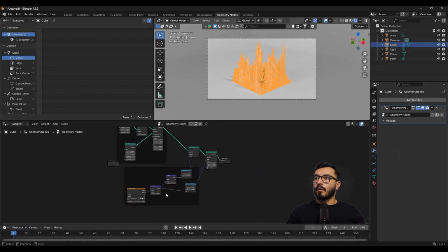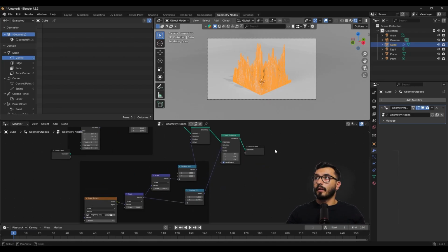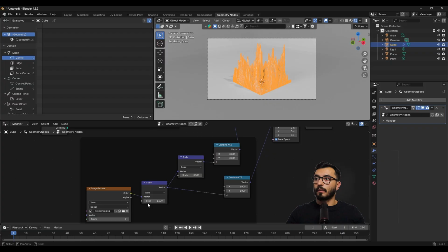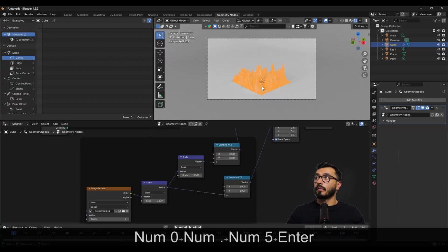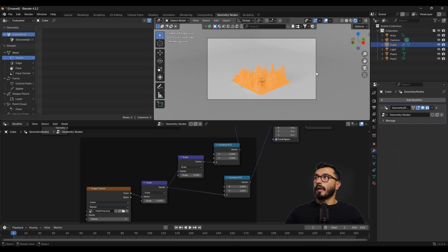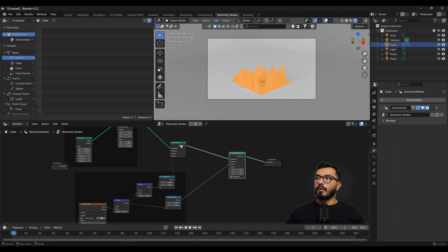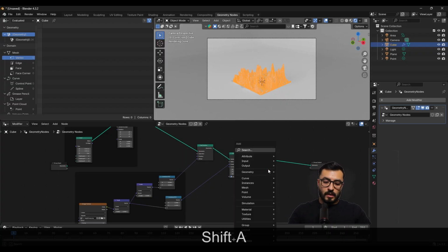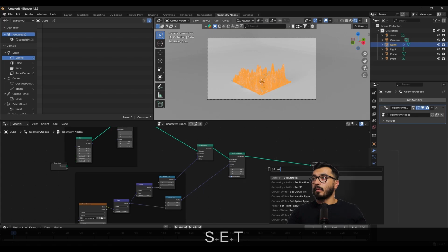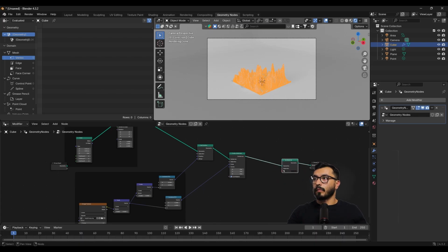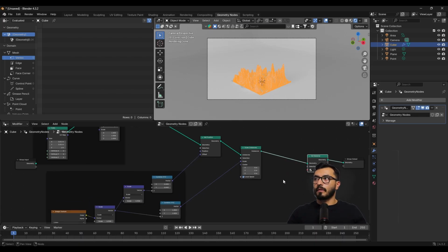Now we can control the height of the bars by changing here. I will just put it to 0.5 so that we don't occlude parts of the height map with too large bars. Now what we need to do to make the color is adding a material. So we will just set material node. We will place it here, then we will define what material is this one.